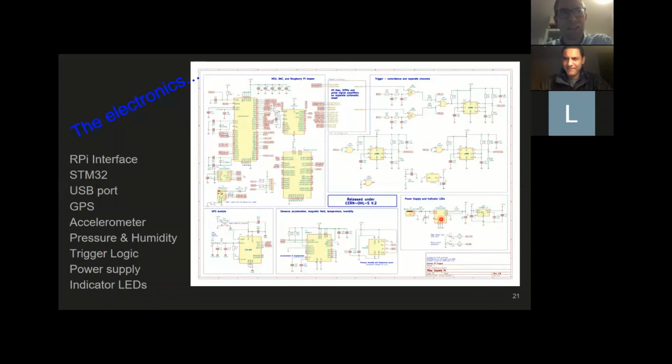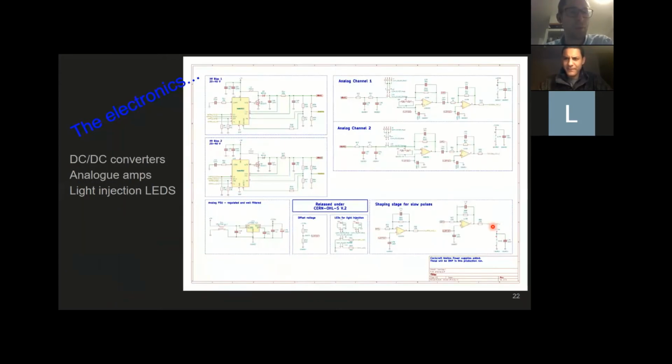And we regulate that down to 5 volts, which is kind of the power voltage. It feeds the Raspberry Pi, which has its own regulator, and it also feeds our DC-DC step-up, because we get more efficient conversion if we start with 5 volts rather than 3.3. And then we have a 3.3 volt converter here, which drives some of the lower voltage logic, and also the STM microcontroller, which is the 3.3 volt part. We have a second page of schematics, and that's it, so 2 pages.